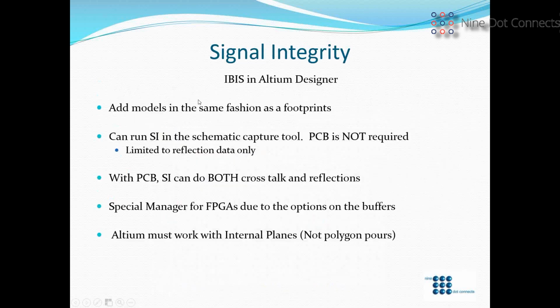All right, so what about Altium Designer? You can add models to Altium Designer, IBIS models, in the same fashion as footprints, whether in the library or in your design. You can run signal integrity in just the schematic capture alone. So if you're just working on your tool and you just want to see reflections, you can do that, okay? But if you want the full functionality of the tool, you really do have to have your PCB completed so that it can add the trace information and its spacing on the traces as well. And so if you've got both the schematic and the PCB, signal integrity can do both the crosstalk and the reflection. Okay?